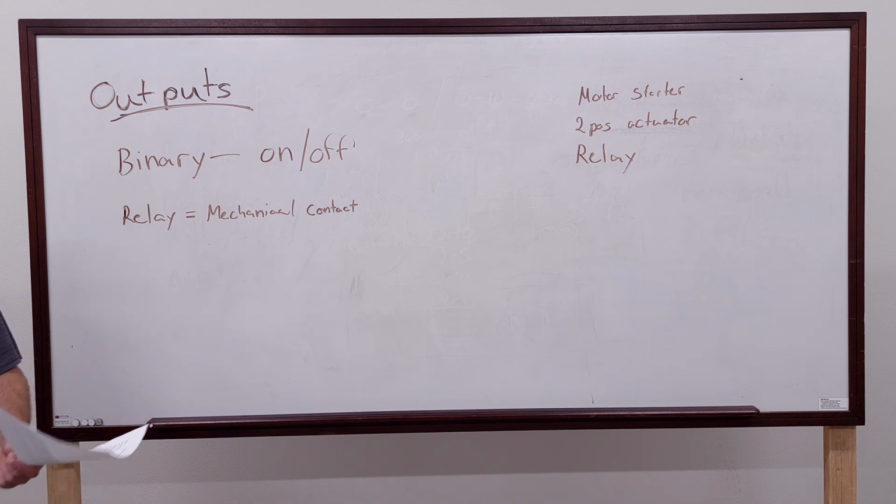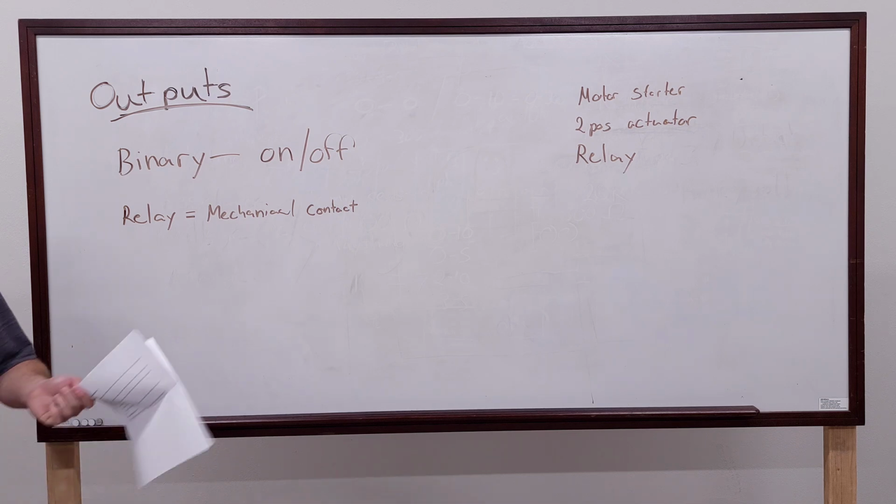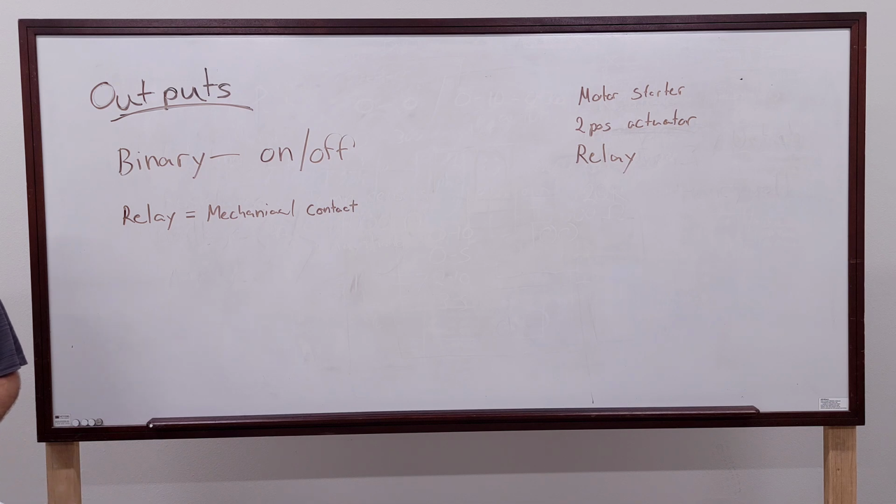We've done it when we have to. There are other companies that do it just for the heck of it to win a job and won't put them in there and don't even tell a customer about that. And then we're like, well, hey, what's apples to apples here? No, they don't have isolation relays in all these controllers. They didn't put a controller with relays in it. They put a controller with Triacs, and we'll explain the whole situation. And then we may win a job because of that. Because we're like, hey, look, we're saving you service calls in the future.